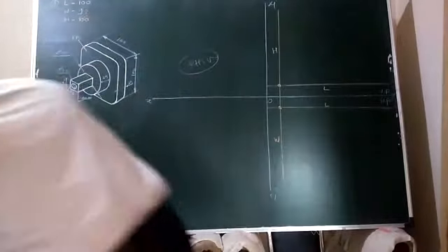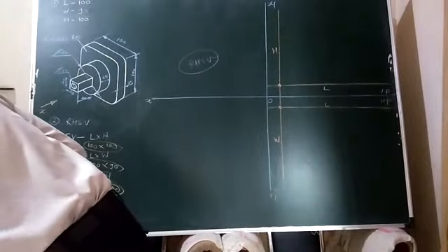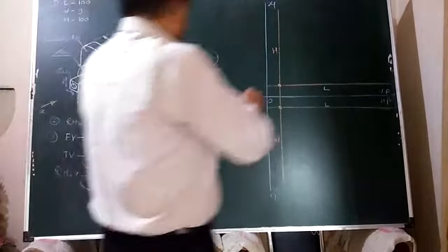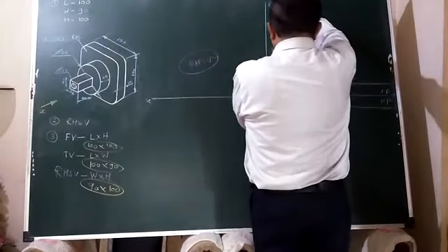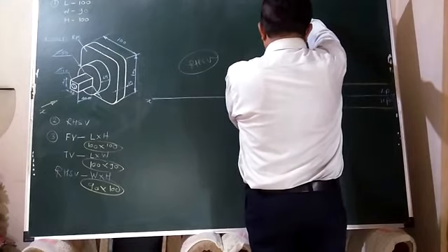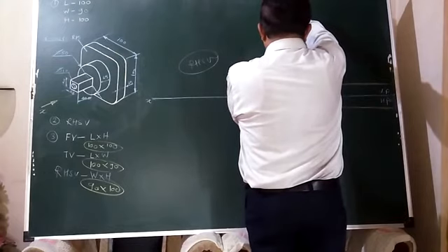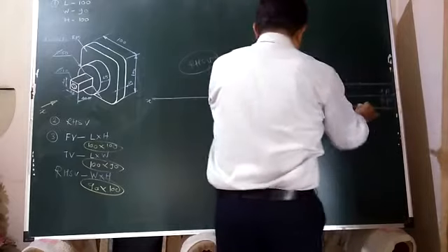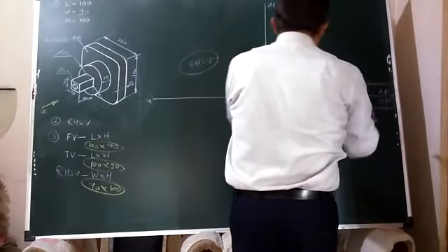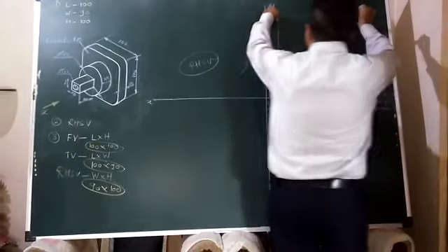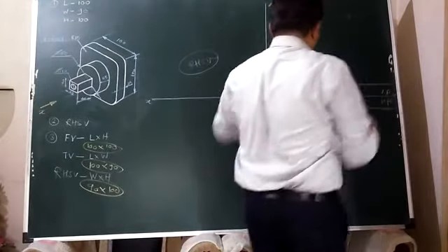So for 100 by 100, approximately I will take this much as 100. By scale only, you have to mark exactly 100 mm over your sketchbook or your drawing sheet on which we are going to construct and complete this exercise.